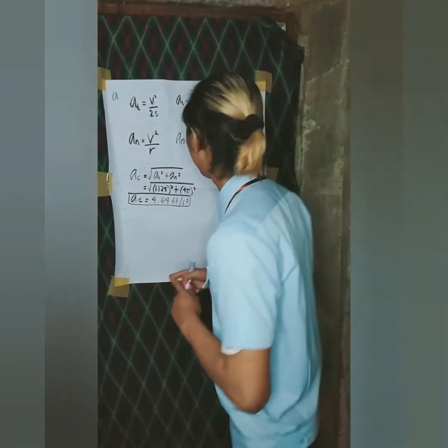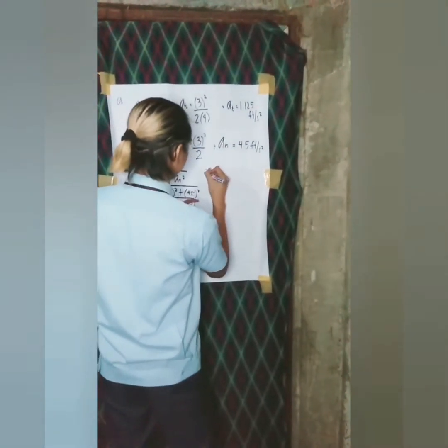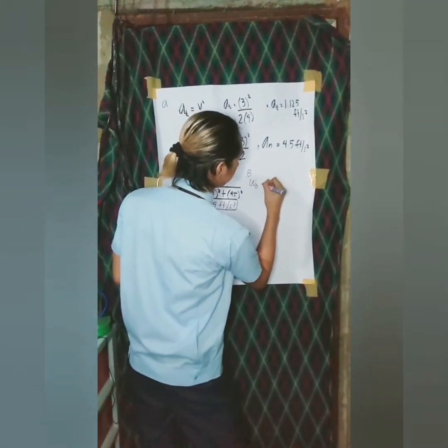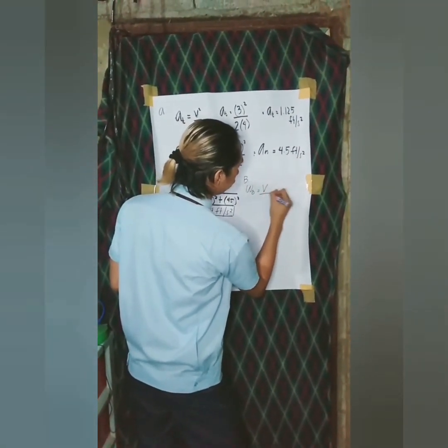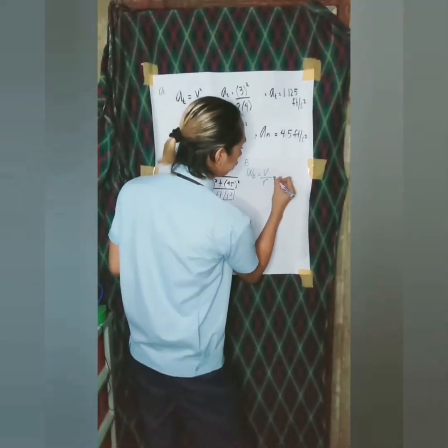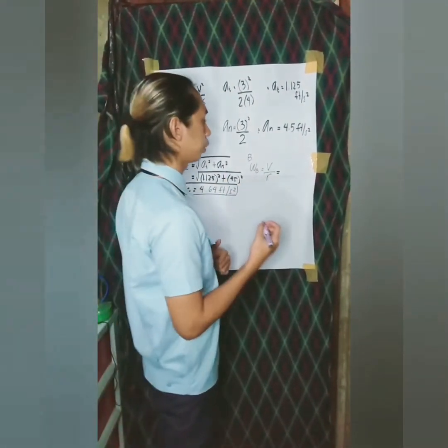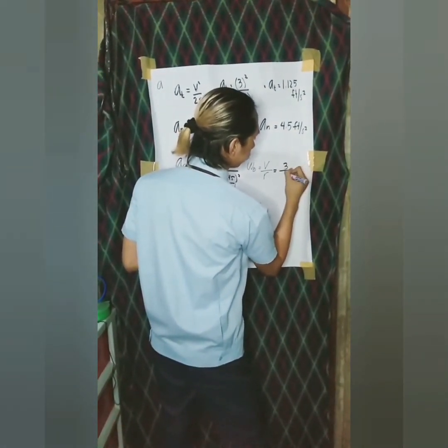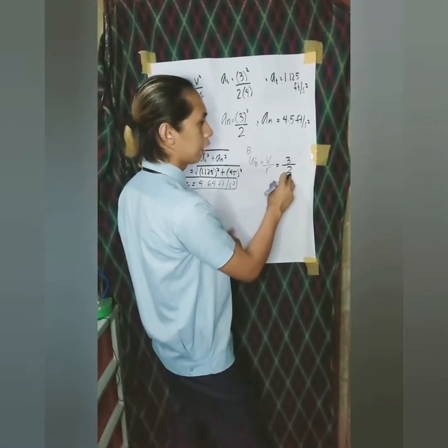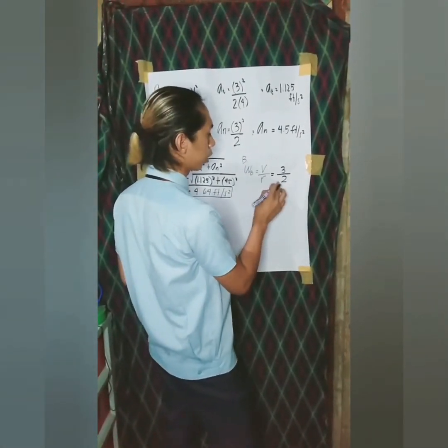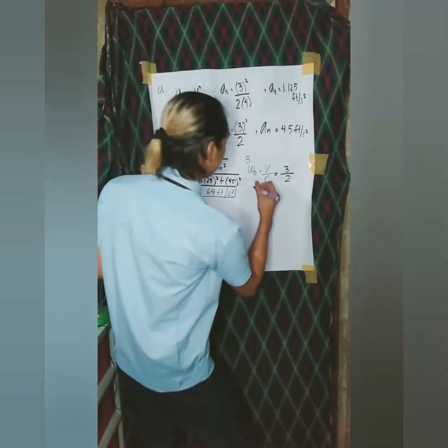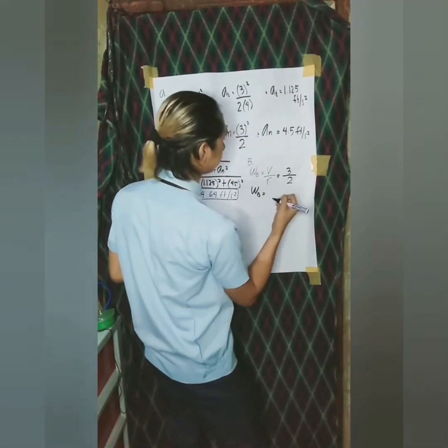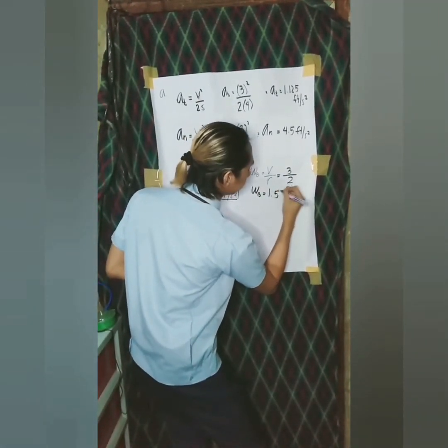So angular velocity B is equal to V over R, where the velocity is given. Substituting the values, 3 over 2, where the radius, earlier in inches, now we use feet. So our angular velocity is equal to 1.5 rad per second.